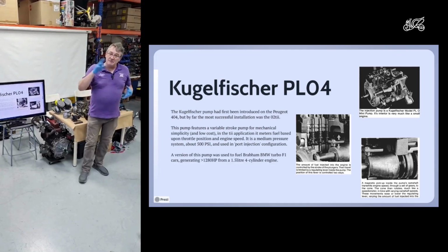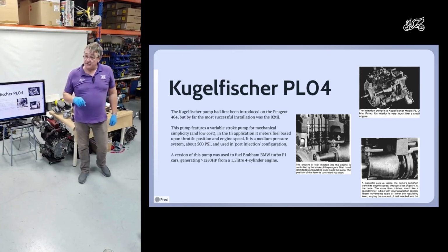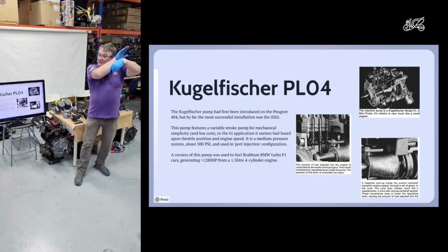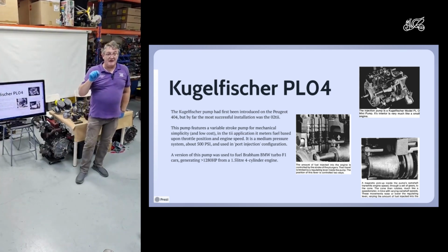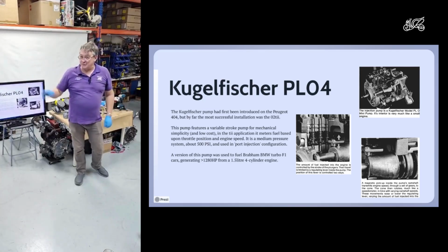And you're doing that because you want to maximize the filling with the clean fuel mixture. But if I now pressurize the inlet with a turbo, when I've got overlap, I'm just blowing straight through and out the other side. Yeah, so I'm blowing unburnt mixture out the exhaust, which is a no-no.